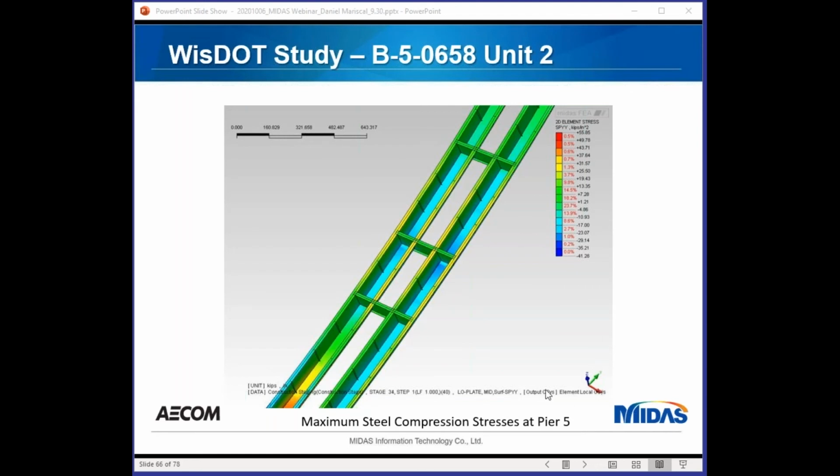This is a view of a little bit further in. The stress is kind of normalized as we go to the other spans. This also shows the fracture happened at the midspan. So that means that since the right side fractured, the left girder had a big positive bending moment.